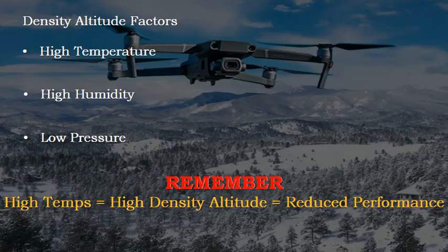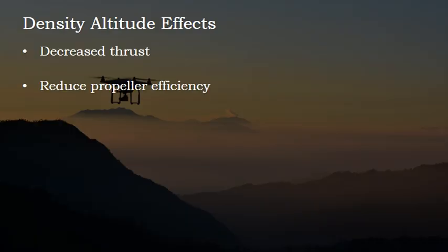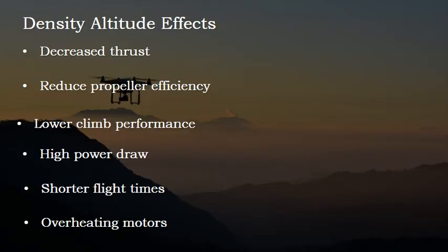Here is an FAA exam trick that you should remember. High temperature equals high density altitude, which equals reduced performance. The effects of high-density altitude on drone flights include decreased thrust, reduced propeller efficiency, lower climb performance, higher power draw, shorter flight times, and overheating motors.